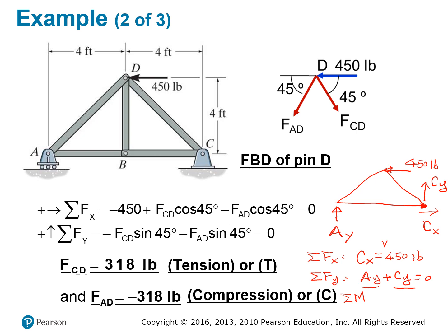You can pick point A, you can pick point C, you can certainly pick point D. So here's the D, here's the A, here's the C. If we select the point C and make this one equal to 0, then Cx and Cy will not make any contribution to the moment because these forces apply to the same point as the reference point.